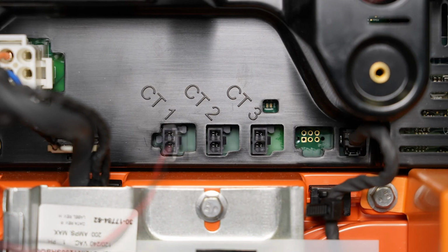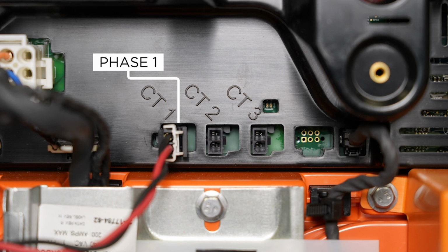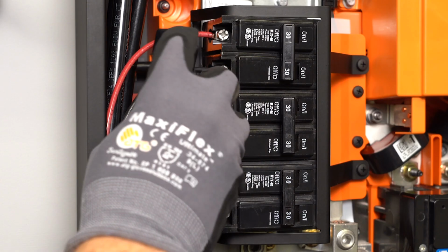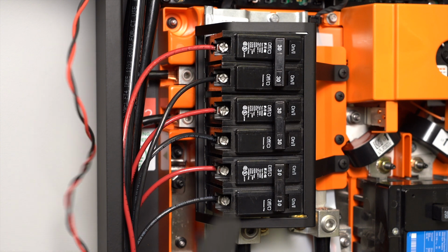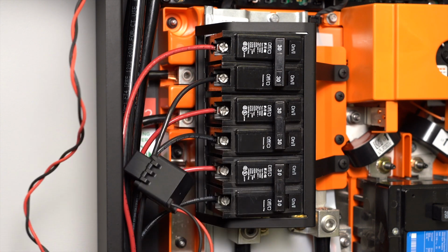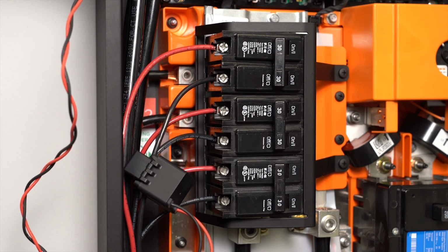Plug the auxiliary solar CTs at the top of the gateway, keeping the phase of each port and CT in mind. Clip the CT around the phase 1 AC conductor with the arrow or label facing toward the direction of the solar inverter. It is preferred to use a single CT for each solar inverter for more detailed monitoring. However, you may group multiple inverters under a single CT. Grouped conductors must be of the same phase. Ensure that load conductors are not included in the grouping.